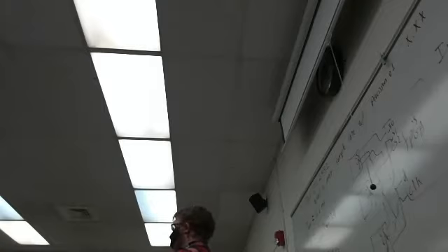Wait, so are you saying that we can control chip select, or is it grounded? So I say you do control chip select. Oh, so with 2 wires you don't, and with 3 wires you do have a chip select. So in the case where you are using chip select, according to the data sheet, what signals the ADC to start a conversion? The clock signal goes up.